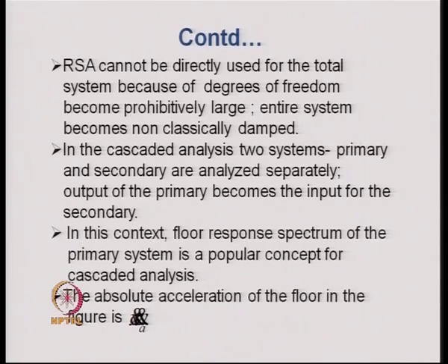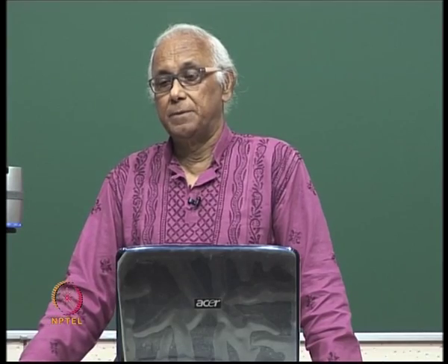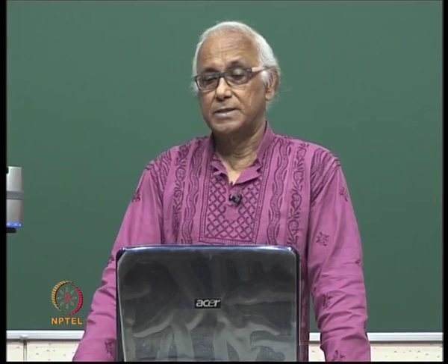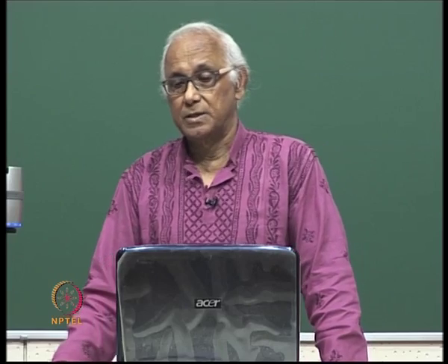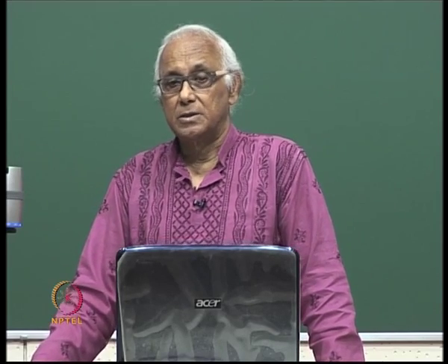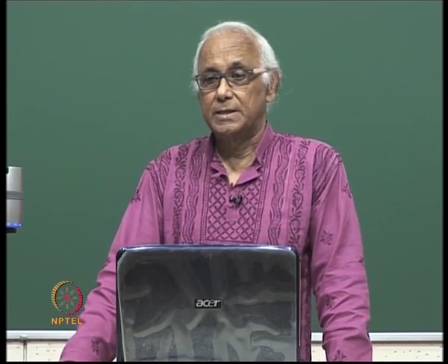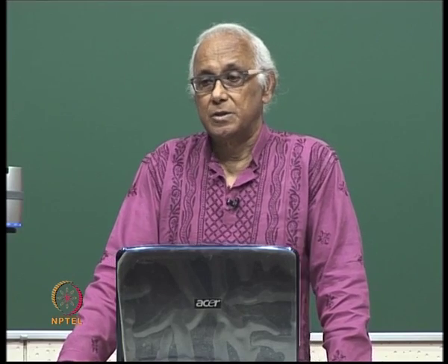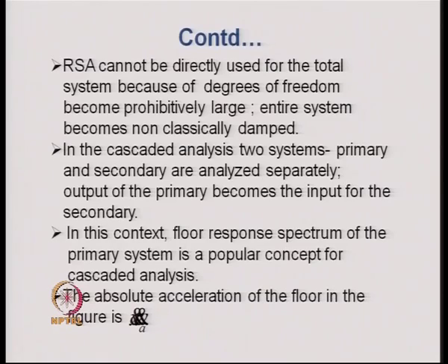In this case, we can consider the basis to be a single support excitation case, that is, we can assume that there is no time lag or phase lag between different supports, and all the supports are uniformly excited by the time history of the absolute acceleration.